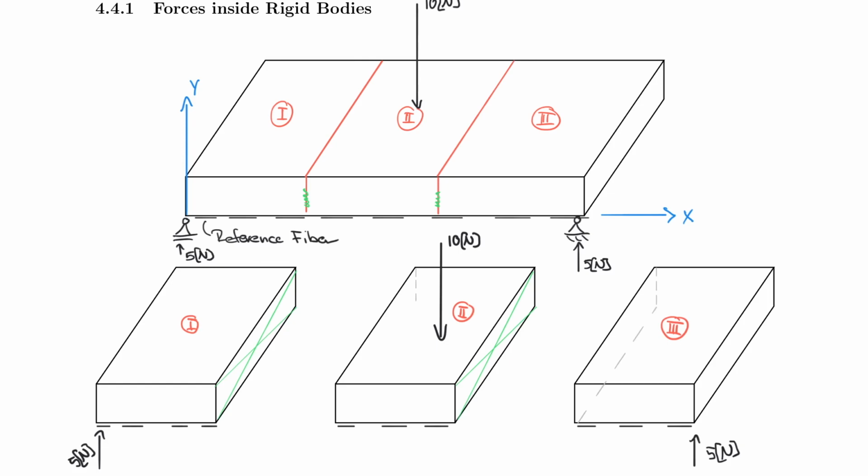And those, of course, have to also carry some forces to transmit the loads between one side of the glue to the other side of the glue. So that's what you see here now with the dashed line. Okay, so now we can ask ourselves, how do I bring this piece, element number 1, back into equilibrium so that it doesn't fall down here on the glued line, because it didn't fall down up here. I just virtually cut the system and pretend that I'm analyzing the glue now.